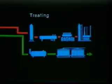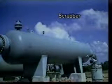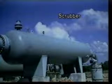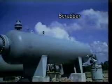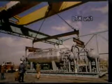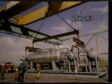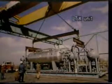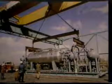There are several types of gas treating vessels which remove condensate from the gas stream. A scrubber is a special type of separator designed to handle streams with high gas-to-liquid ratios. Often a scrubber is used in place of separators for wells that produce very light oils or condensates. The gas and condensates separate by gravity action within the scrubber. Another method of separating liquids from a gas stream is through low-temperature extraction. Essentially, the process causes the pressure of the gas stream to be reduced by having it flow through a choke, causing a sharp reduction in the temperature and the condensation of water and liquid hydrocarbons.